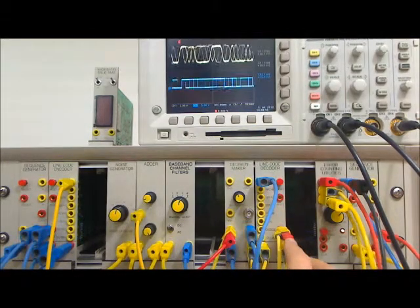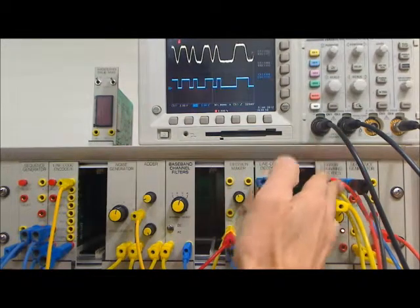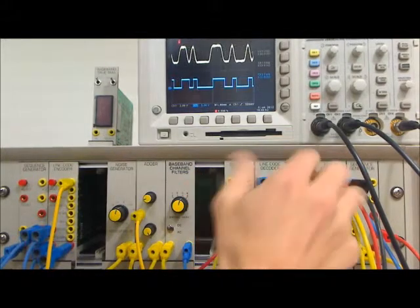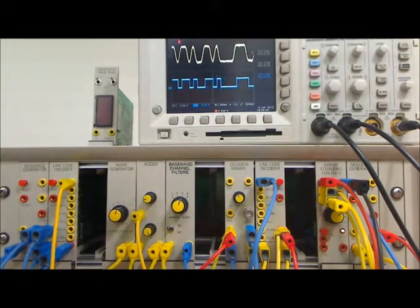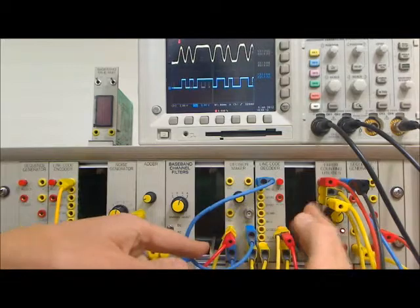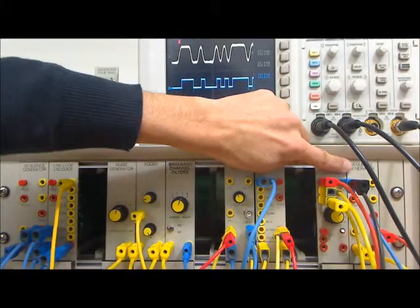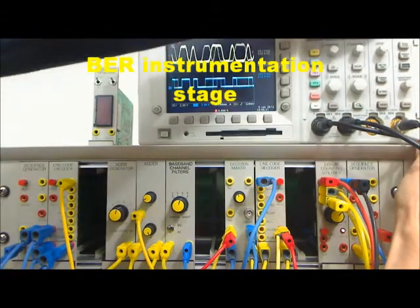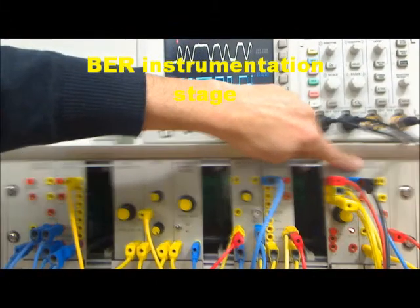Now what we have to do is count the number of errors in that signal. So we'll use the error counting utilities module, which comprises an exclusive OR function which acts as our comparator. What we do, we take the signal from the decoder and we compare that with a local sequence from a local sequence generator. We have a second sequence generator module.